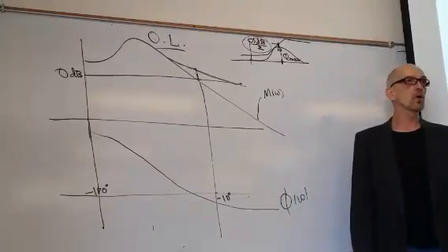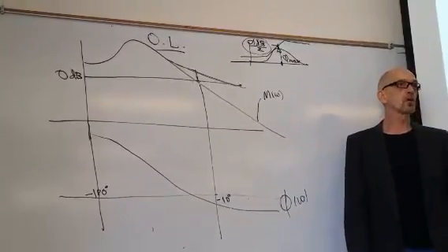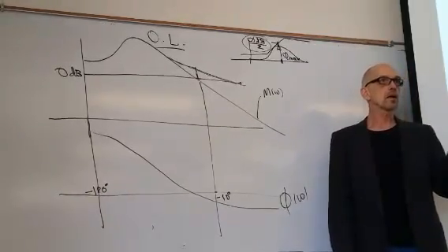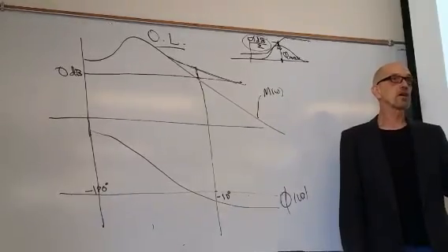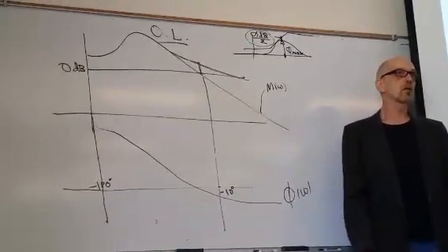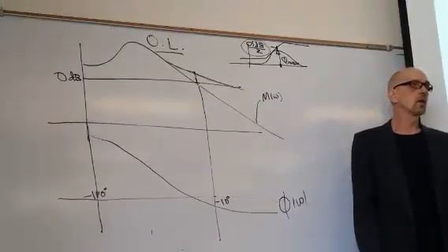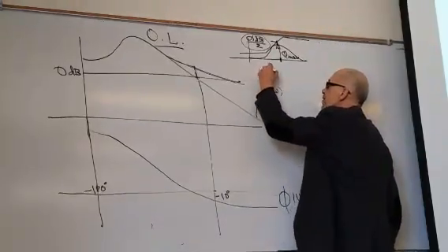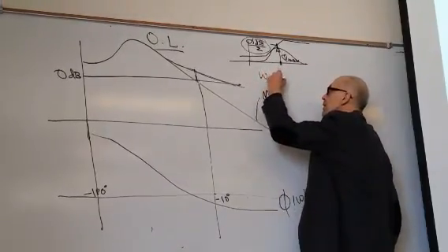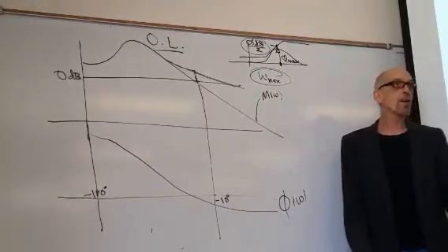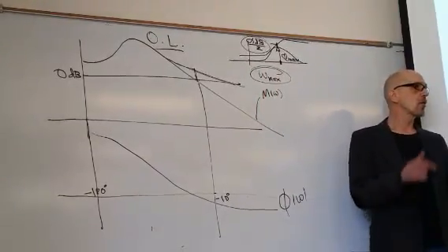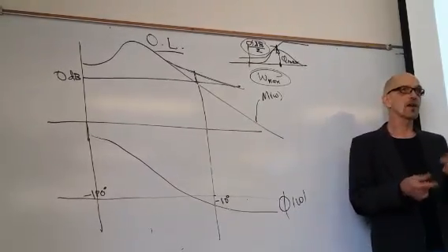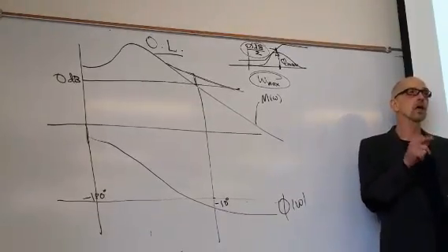So then what you do is you compute alpha. You've got these two equations, right? You have the phase margin, that's one equation. And you have alpha. That gives you your two equations and two unknowns, omega 1, omega 2. Then you find the omega max from the compensator, because remember there's omega 1 and omega 2, but omega max is the square root of omega 1 omega 2. So once you find omega 1 and omega 2 from those two equations, you get omega max.